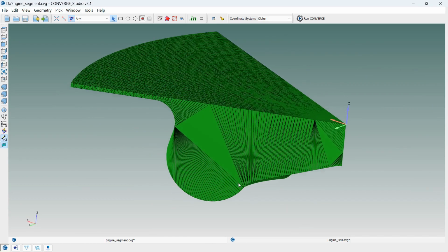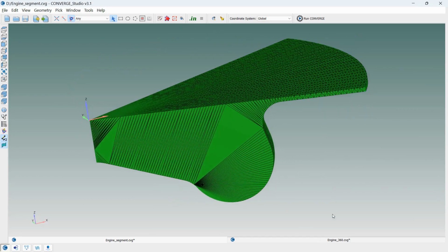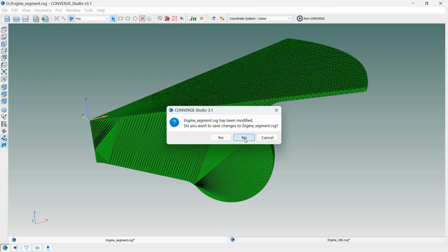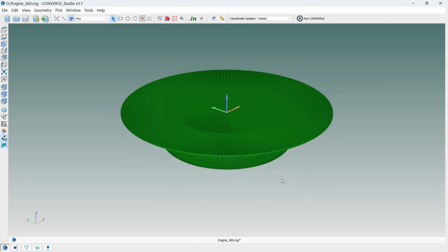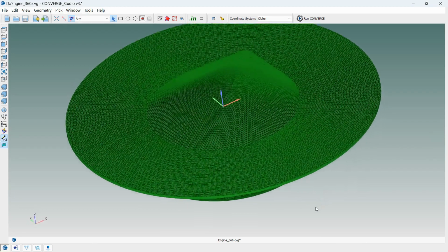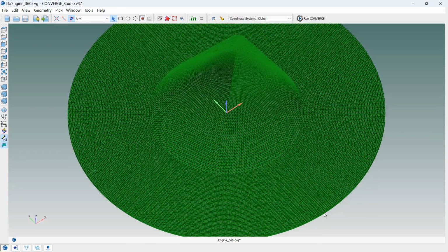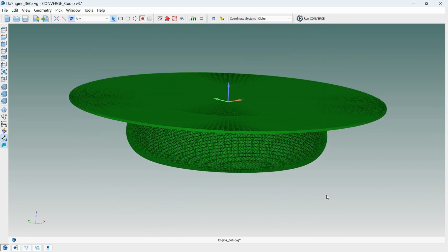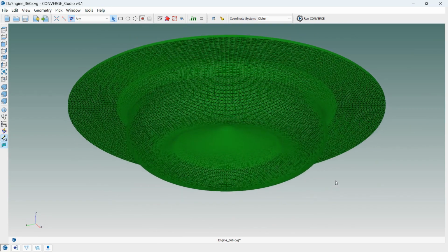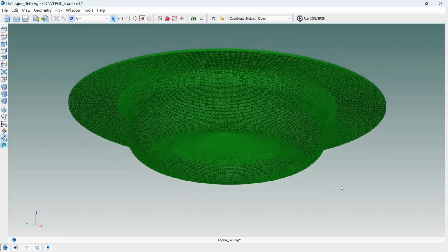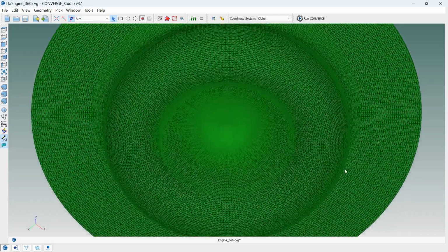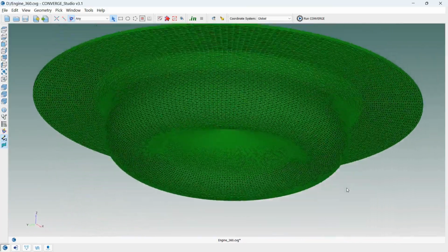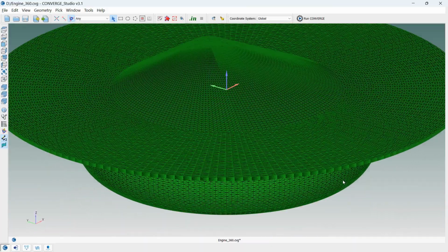As you can see, the mesh on this geometry is very small. You should know that the Converge calculations have nothing to do with the surface mesh quality, and the smaller the number of triangles, the faster the solution speed. What is important here is the smoothness of complex places like the piston bowl. To have a proper and regular surface grid, use meshing software and import the file in STL format in Converge.